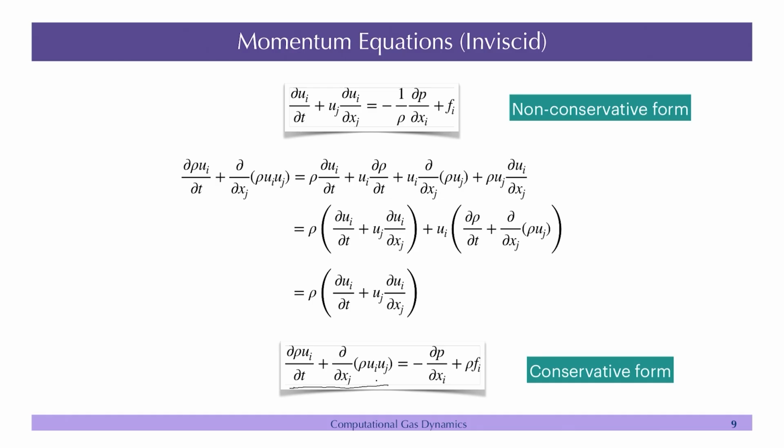So, what changes do we see here? We see that rho is now absorbed in the velocity. Instead of talking about the primitive variables, which are rho, u, v, w, we are talking about rho u, rho v and rho w. But why do we want to do that? That is the question, because in incompressible flow we do not do that. Anyway, we do not need it because rho is constant there.